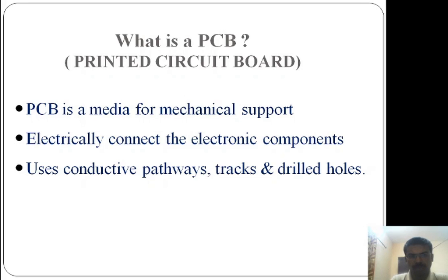So first of all, we should know what a PCB is. It's a printed circuit board. A PCB is a medium for mechanical support and for electrically connecting the components, that is, electronic components. It uses conductive pathways, that is, conductive tracks and drilled holes. Drilled holes are used to place the components on the PCB and solder them.